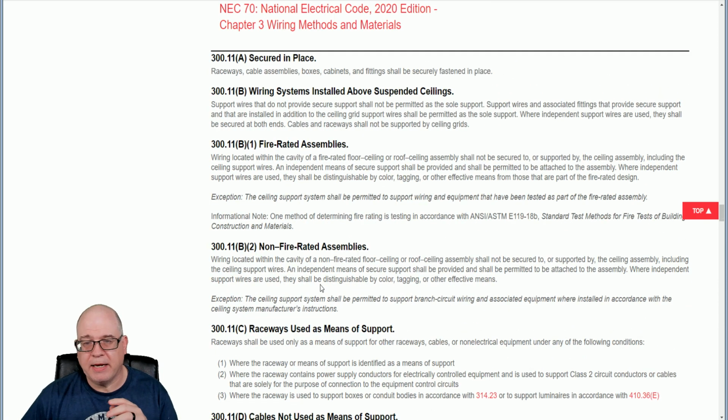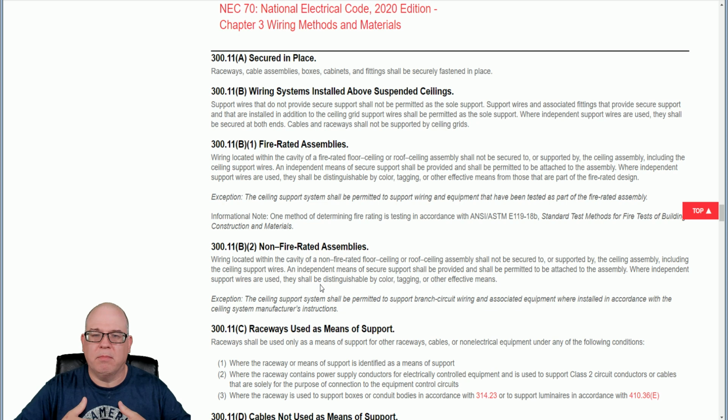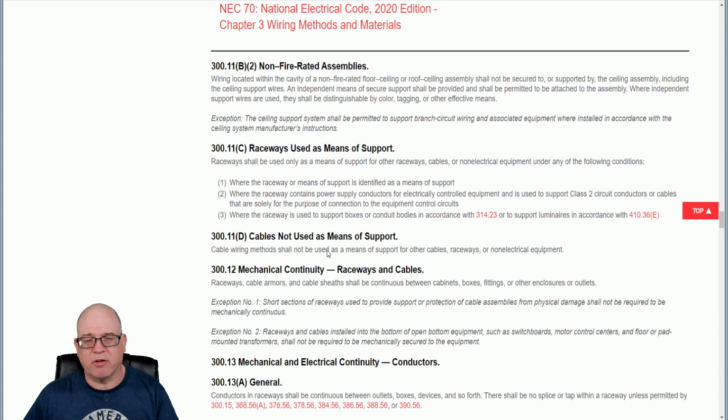And also remember that if you get a lot of questions that are talking about general wiring applications, it's going to be in 300. That's the general catch-all area. Then it starts getting specific to the wiring methods in chapter 3. But the general requirements, for example, depth of cover for raceways underground, that's under 300.5. I mean, that's in the general requirements. So as you start to learn, it makes it easier for where you need to go. But it just takes time. And that's what we developed our Fast Tracks program to do.